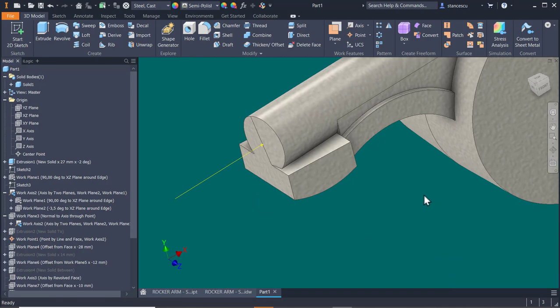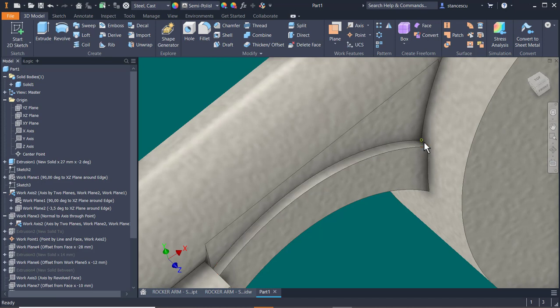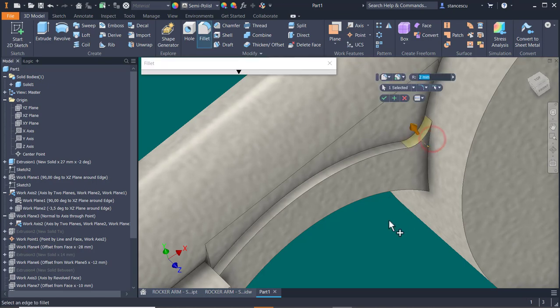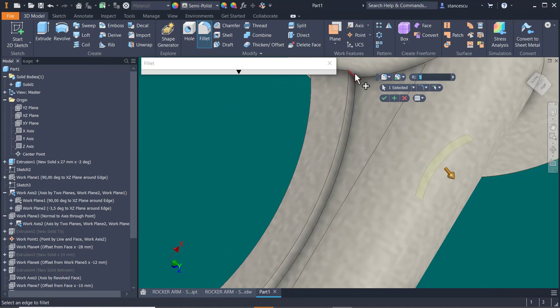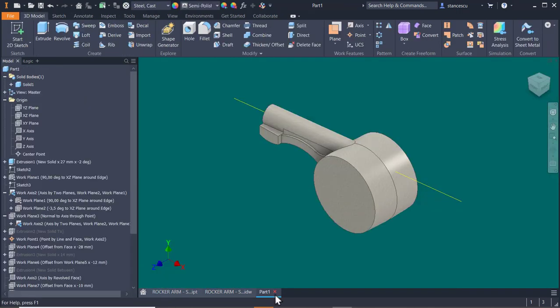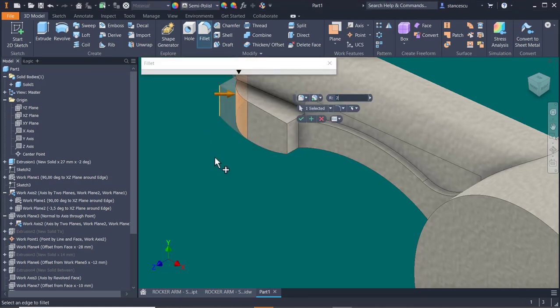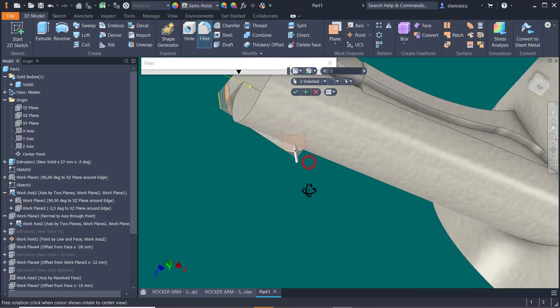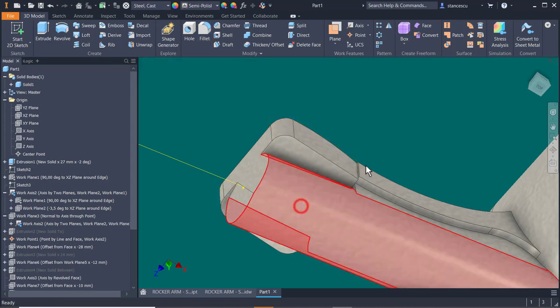Another thing to do is to apply here a radius of 5, and now we apply fillets of 5 to these small edges, as you can see. Other fillets are for these edges of 2, but only 3 of them, because this is inside. Good.